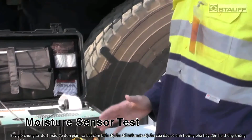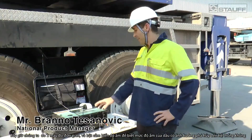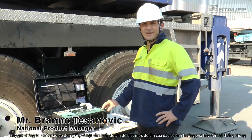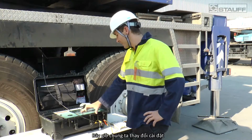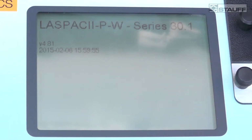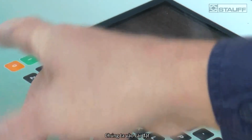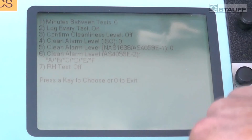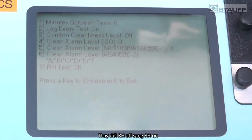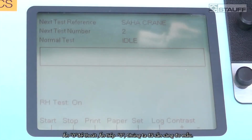So now we're going to do a similar test, but this time we are going to turn our moisture sensor on, as water is also very damaging to our hydraulic system, so we want to see the moisture content of the actual oil. So I just need to change settings. We turn the particle counter on, we go into the settings, and in the test options menu, press 6. Change RH test off to on. So press 7, change to on. Press 0 to exit, 0 to exit again, and we're ready to take the test.